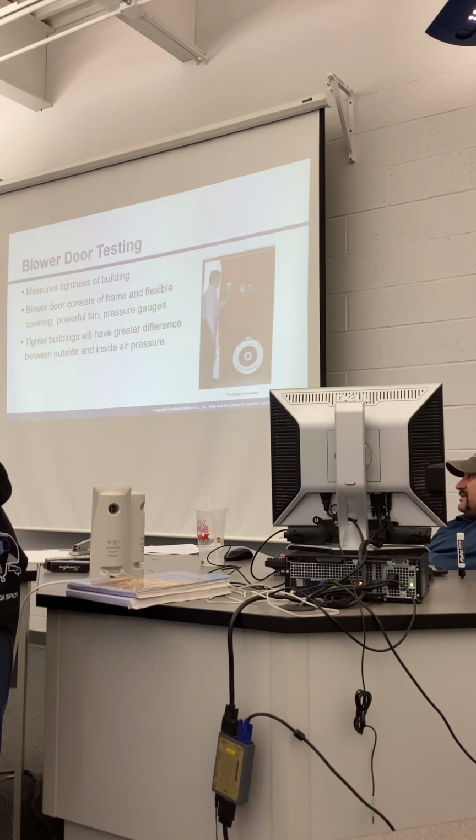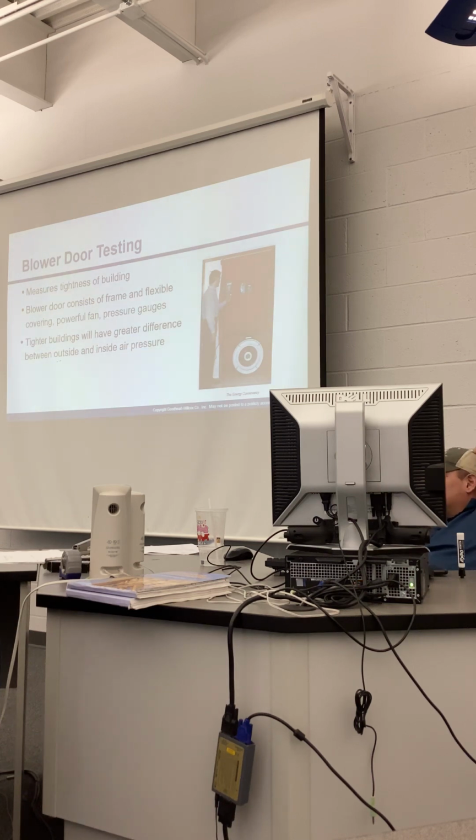I mean, it's like, okay, let's go caulk up every one of these windows and now let's spend $5,000 on an air evac unit. It's not even called an evac, it's called air infiltration system. So, would you rather just bring in a little bit of cold air around your windows or spend $7,000 to bring in tempered air into the building? Because that's really what it is.